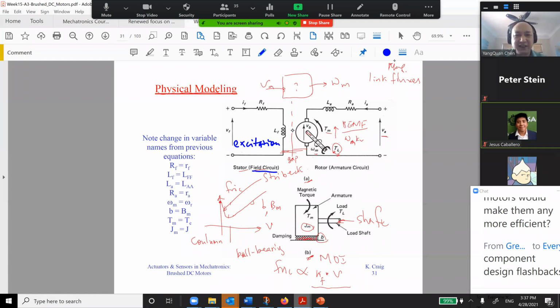So then how fast this one will move depends on the I, okay? So we know that answer. All these coefficients in here, this is called the electromechanical part, the motor part. This is called the load part. So you have two parts, okay? You have an electromagnetic torque, TM, where M stands for motor. And then you have the damping, viscous damping coefficient B. You have a load, okay? This is a shaft to connect to a load, okay?